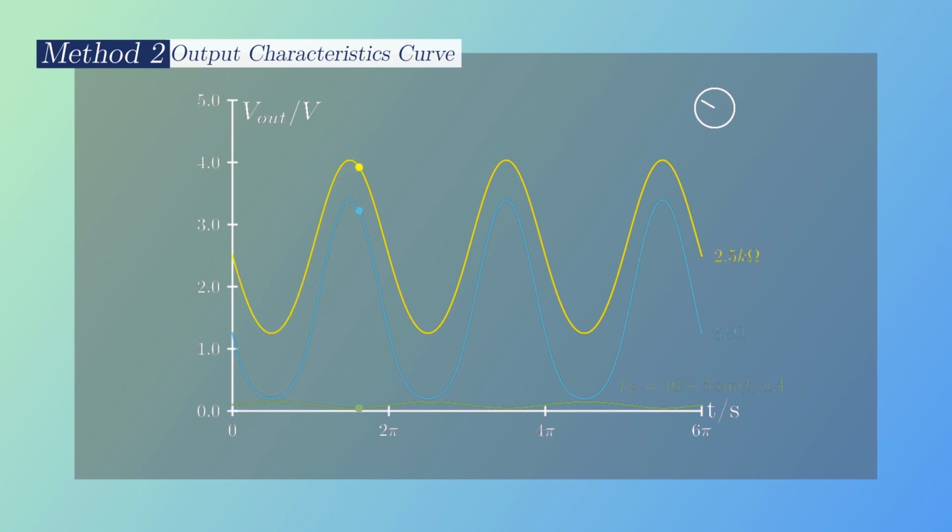As we come towards the end of the video, I would like you to pay attention to the difference between these two waveforms. The 2.5 kilo ohms resistor has been chosen specifically, which means linearity is conserved, and it's very sinusoidal indeed. But what happened to the waveform of the 5 kilo ohms resistor? Although it's sinusoidal, it looks a bit odd, especially with its troughs. Why is this the case?